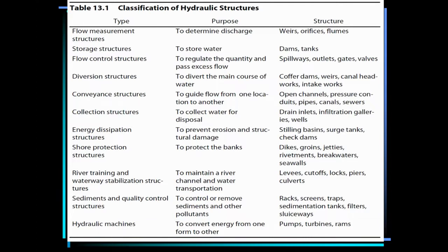The underground storage tank is used to collect water from the water treatment plant, and then a pump is attached to the underground storage tank to pump water to the overhead tanks, so that water will flow by gravity to all the various toilets, kitchens, wash hand basins and what have you.